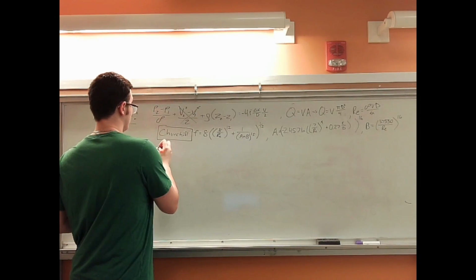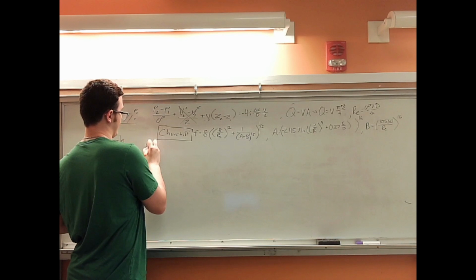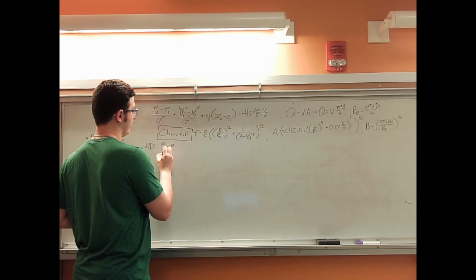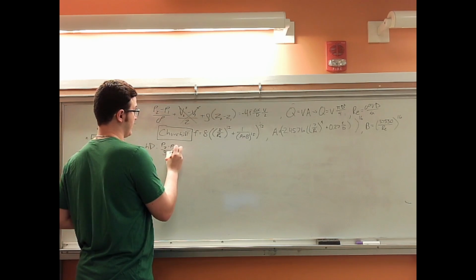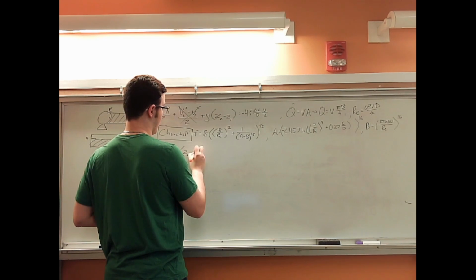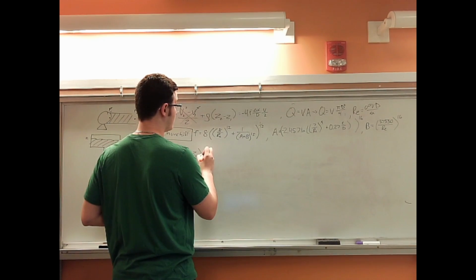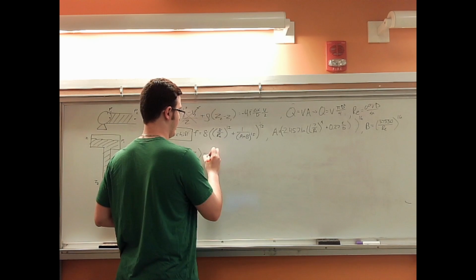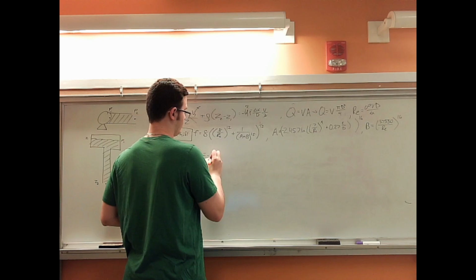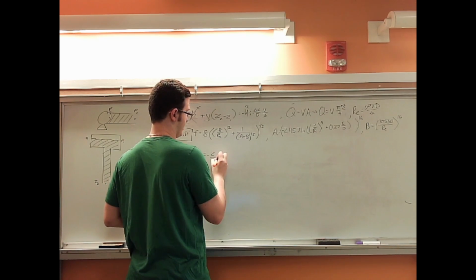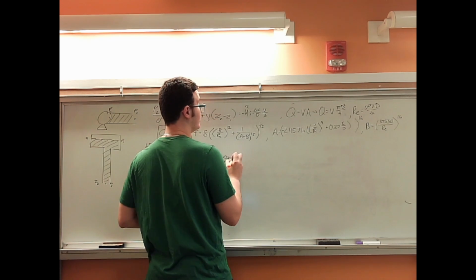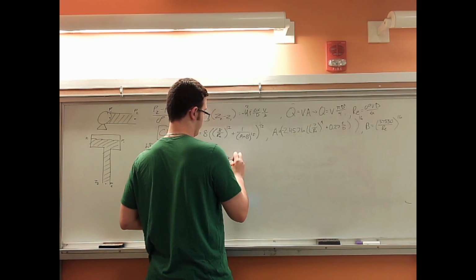So basically all we're going to do is divide g, the gravitational constant, across. That's it. So head drop, we'll call it HD, is the pressure difference between states 1 and 2 divided by gravitational constant and the density plus the difference in height between states 1 and 2 equals negative, these cancel out, so 2 divided by gravitational constant times the friction factor times the change of position divided by the diameter multiplied by the velocity.